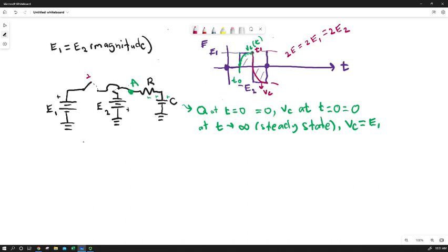This is going to involve a little bit of calculus. We're going to try to not make that a big part of the focus here, but mainly focus on the electronics and how Kirchhoff's voltage law and the definitions of voltage drop over resistors and capacitors end up defining the time-dependent expression for the voltage drop over our capacitor, which is something we are going to measure on our proto board with a signal imposed by our arbitrary waveform generator or function generator.